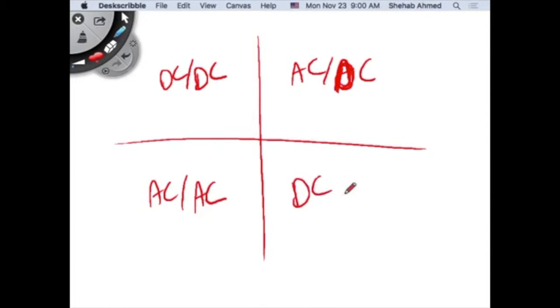The last sort of area, or converters, that we would like to discuss are the DC to AC converters, and these are called inverters. Right? We discussed a little bit about inverter operation in our rectifiers topic, and this was a very special type of inverter. I mean, it's a thyristor-based inverter. They are used typically at very high powers because thyristors are very rugged devices that you can use at high power.